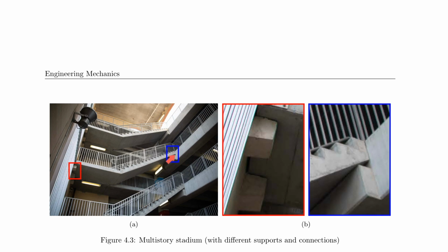So engineers want to make sure that if, for example, this part of the structure is exposed to heat and it extends or changes its shape or its dimension, that it still does not affect this part of the structure negatively. So this portion has to be somewhat decoupled from this portion, and the way engineers deal with that is with, for example, neoprene pads that then create a certain support reaction or a certain type of support reaction.